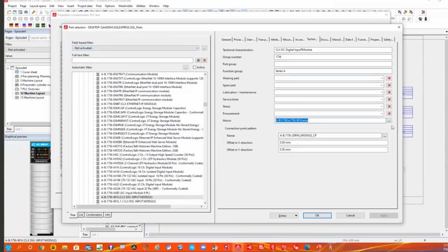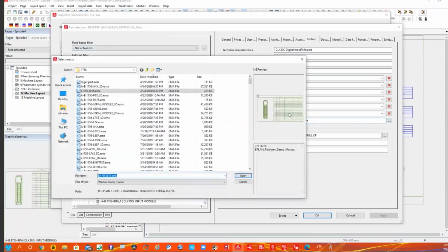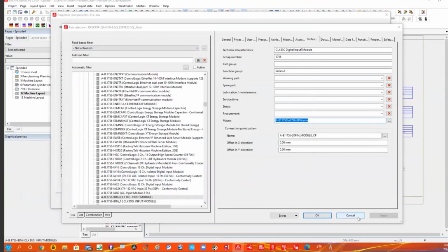So this macro will be utilized to create. This is an overview, but you do have multiple representations for this particular macro. You could have a multi-line schematic, a single line, an overview, a whole bunch of them. These will be the ones represented and used in the auto generation. So it's up to you to fine tune it.